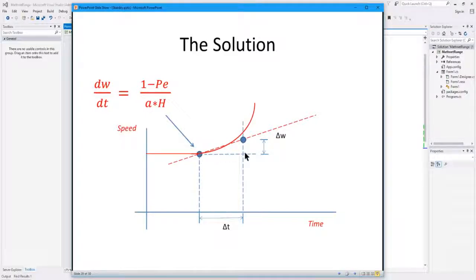So then I can go out to here, get this new value of speed, and once I've got this new value of speed, it gives me an estimate of the generator speed or position or angle at this point. Then I can go back and resolve my load flow for this new electrical power at this point using this estimate of generator position. And then I can resolve this, get a new constant that has a different slope at this point, and I can keep doing that.